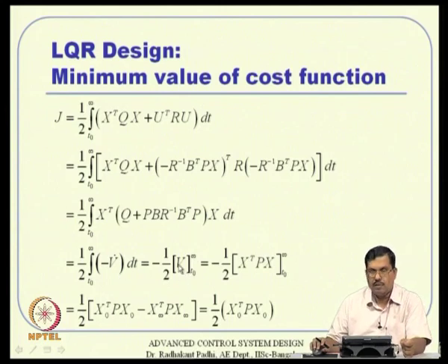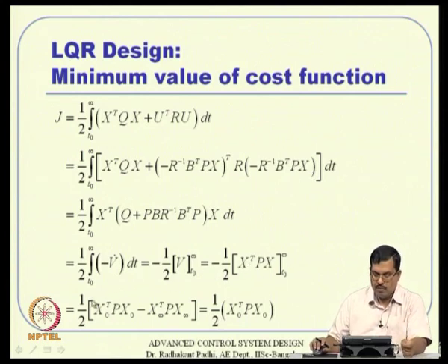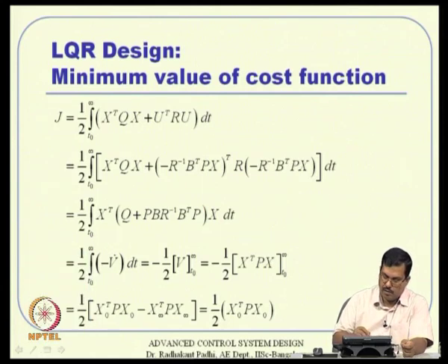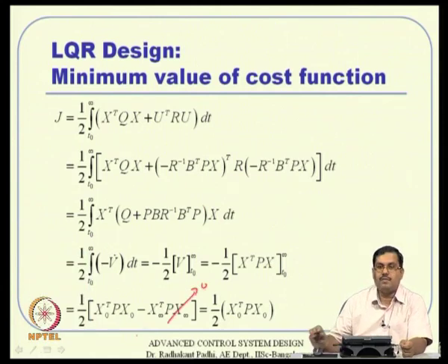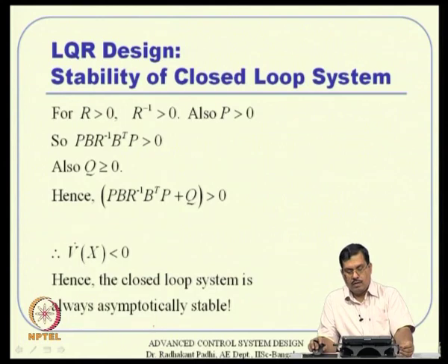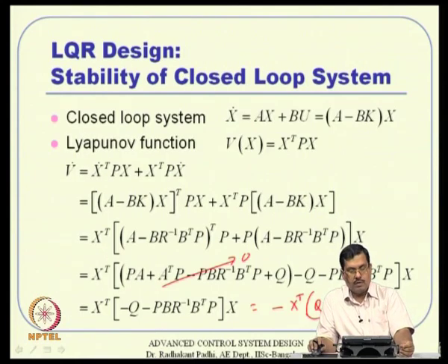So, I can just simply take V from T0 to infinity, and you can evaluate that, and it turns out to be like that actually. So, if I evaluate this term, the negative sign is there, remember that. So, infinity minus T0, with the negative sign included, it is the initial condition minus the final condition actually. Now, the final condition, x at infinity, is 0 anyway, because that is what we are guaranteed to get using this asymptotic stability condition and all that. Okay.